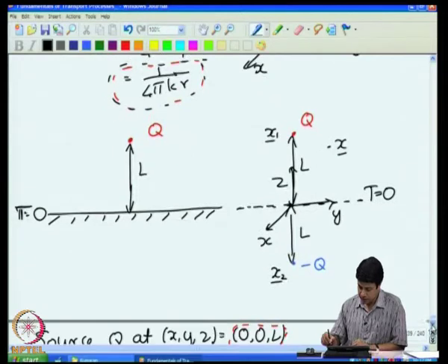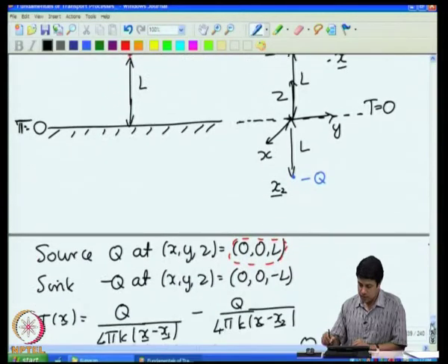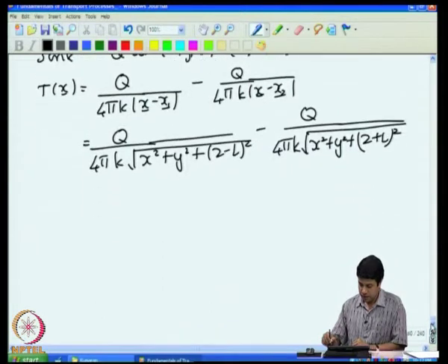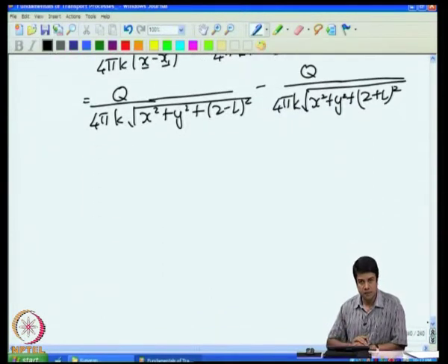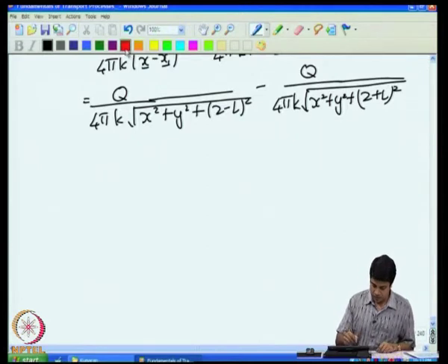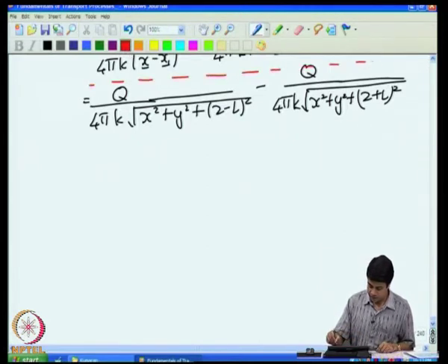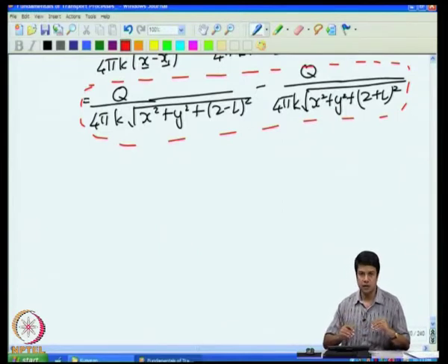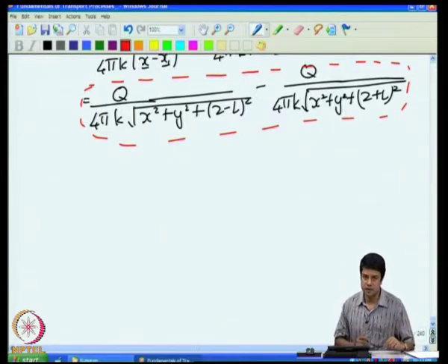So, this was with temperature equal to 0 at the surface. In many practical applications, one will have a heat flux equal to 0 at the surface. So, this is the Green's function for 0 temperature at the surface or for a fixed temperature at the surface, because I can always define a rescaled temperature in such a way that the temperature at that surface is equal to 0.